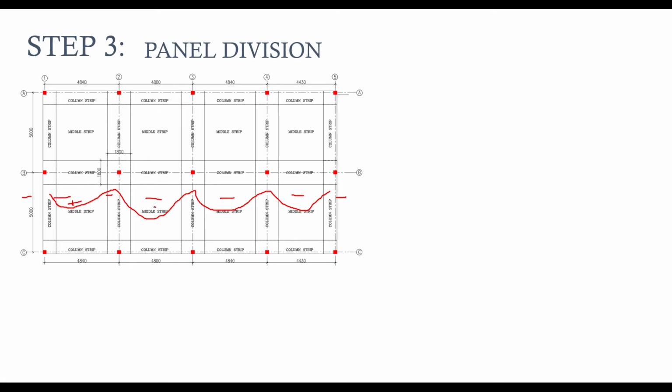This is where we have the negative moment. This is positive, this is negative. This is positive, this is negative. You can now see that the column strip along the y direction, or along this direction, is majorly on the negative. But if you cut your section close to where we have the drop panel, so that means you are going to have something like this.